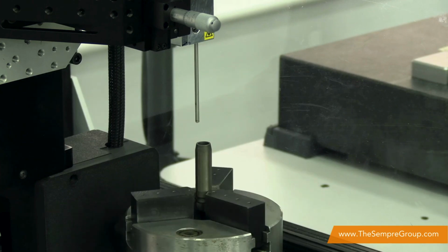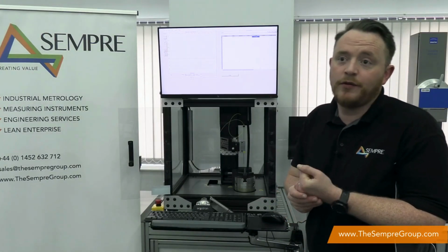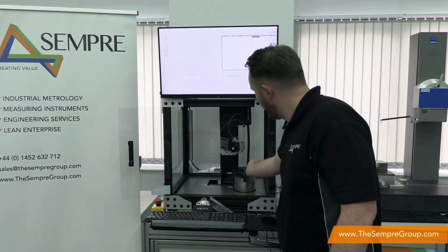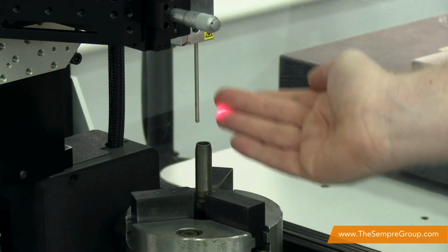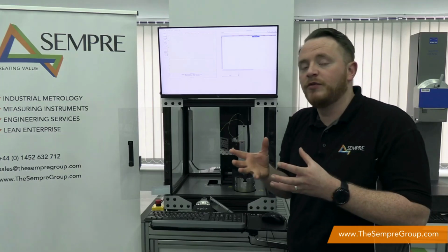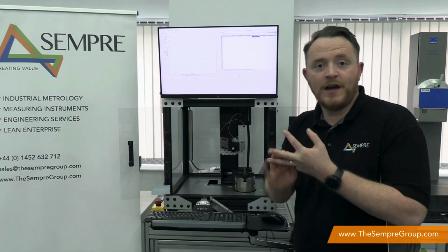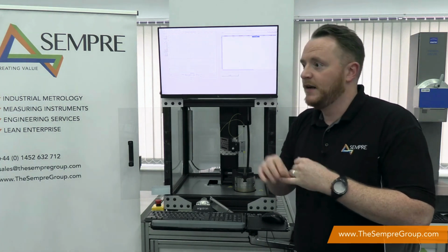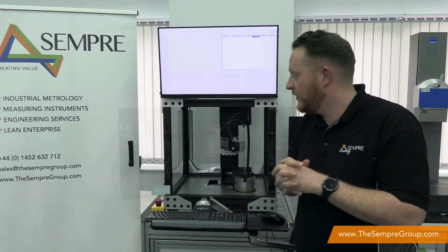So the principle of how the system works is the technology that's used is laser interferometry. If you were to zoom in onto my hand, you can see that there's a spot size. As we take a measurement, the probe will drop down into the component. We rotate the component at the same time and we build a 3D geometry of the surface. From that we can look at cylindricity, roundness, diameter measurements, radiuses, thread measurements and also roughness within certain parameters.